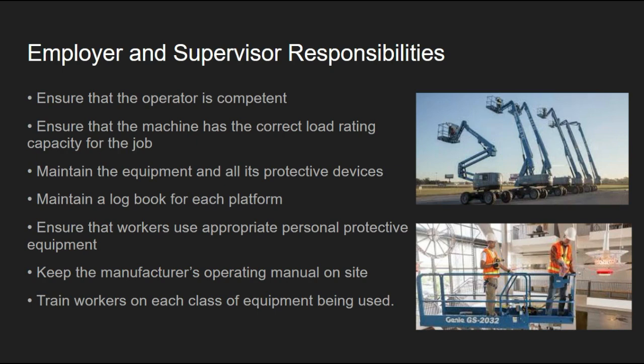We have to fill out a logbook for each platform. So every time there's an inspection, ensure that the workers who are using the lift are using the appropriate personal protective equipment. Keep the manufacturer's operating manual on site, usually stays in the manual basket. And you have to make sure that all the workers are trained for each type of equipment on site. So if it's a scissor lift or a boom, depending on what type, that worker has received practical training for that specific lift.